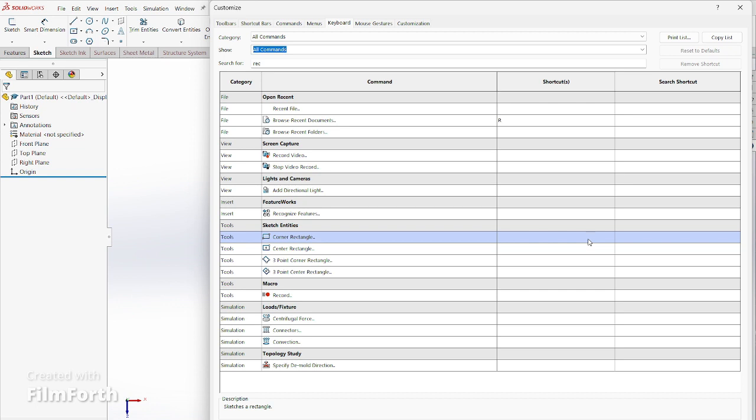Are there others we can use? You can look online to see how other people set up theirs. But if you go back to SolidWorks Tools and try to remodify it, it's going to cancel out the other functions we saw. It will say the R has already been assigned to another function, do you want to replace it? If you choose yes, you're going to be confused later on and might mess up the shortcuts already assigned for that specific reason.